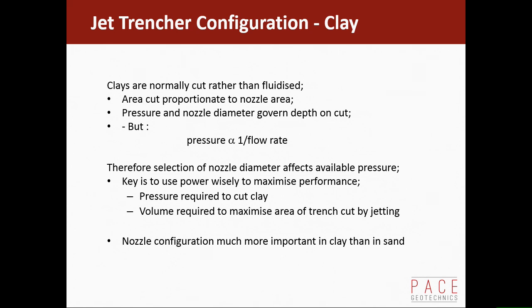Clays, we're normally cutting a clay rather than actually fluidizing it, and that tends to leave some lumps of clay. But with the right nozzle selection, we'll break it up into manageable sizes, and then the backwash moves the soil back down the trench. It's much harder to set a trencher up for clay than it is for sand.